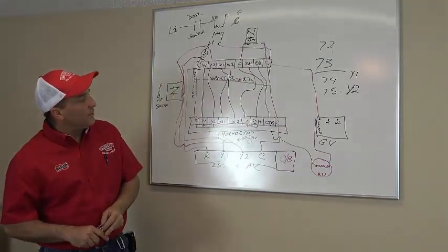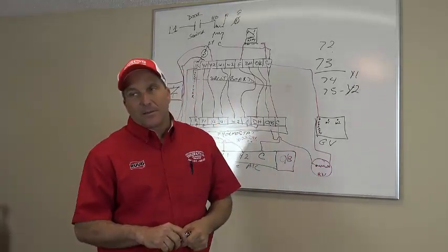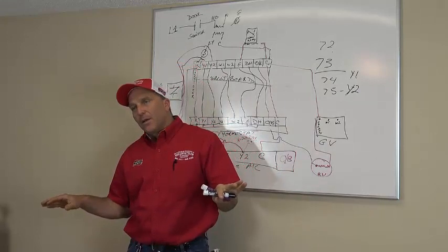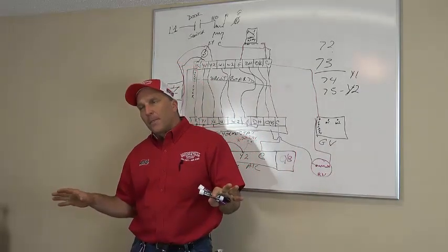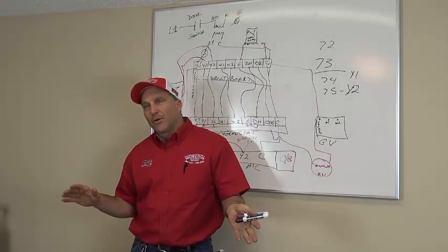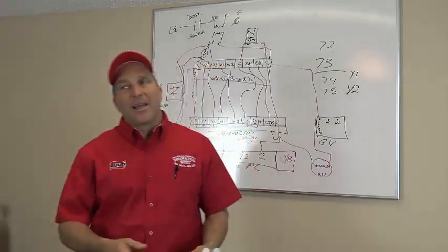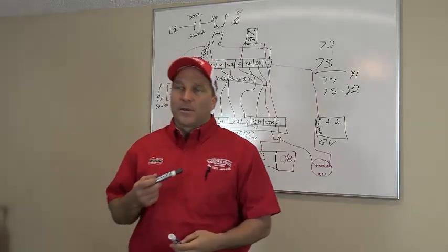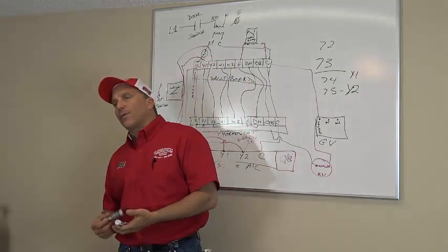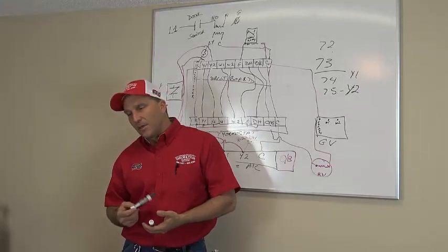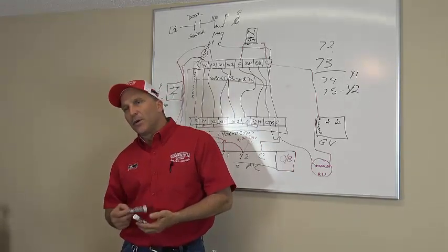W1, W2. Gas heating system. Straight gas heating system. No heat pump here, guys. Okay? You turn your heater on. You set your thermostat at 70 degrees. When it reaches 69 in the house, first stage of heat comes on. How much capacity are you running on a 100,000 BTU gas heater in first stage? 70%. 70% capacity. At what blower speed are you running now?